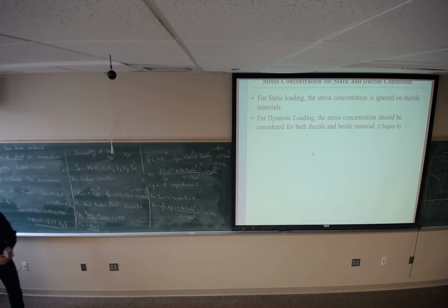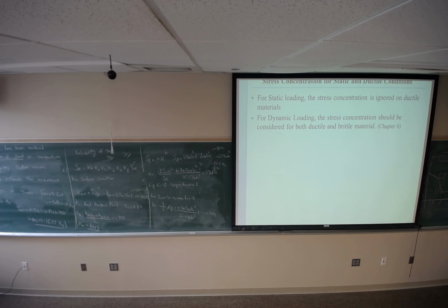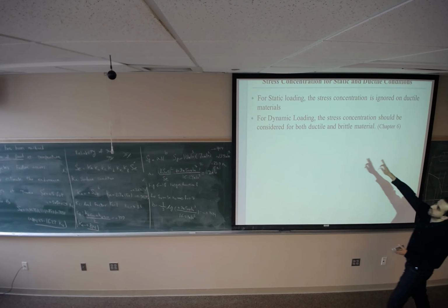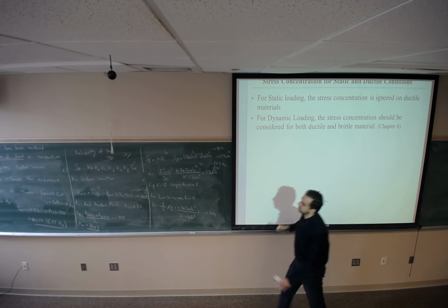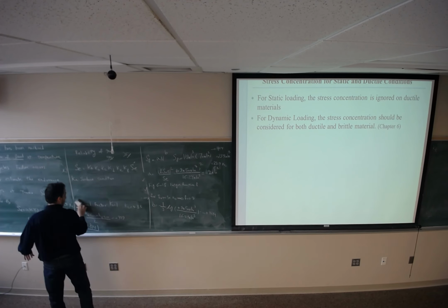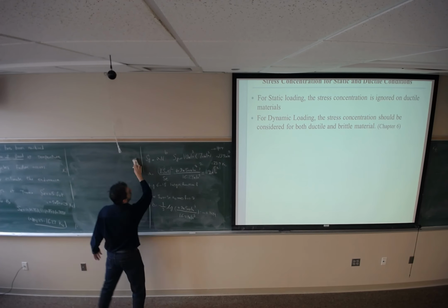For the static loading that we covered in chapter 5, the concentration factor should be ignored for ductile material. But for dynamic loading, as in fatigue problems, we should look at KT, the stress concentration factor. It's the reason that we need to study the fatigue concentration factor in chapter 6.